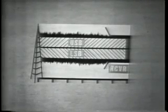When we have 2 sidebands, the receiver bandwidth required is twice that needed for single sideband reception, giving us a lower signal-to-noise ratio. But now that we have eliminated one sideband, the receiver bandwidth may be narrowed considerably.